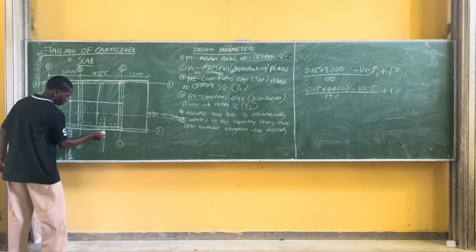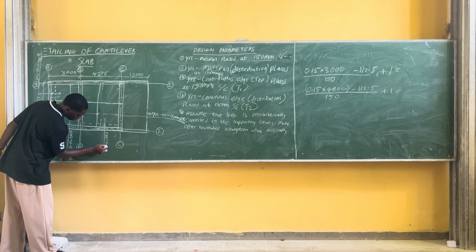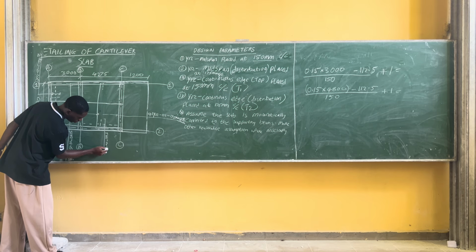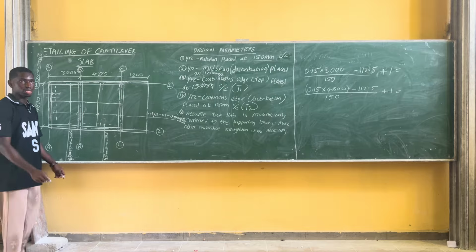So I'll put here 5Y12 bar mark 04 at 150 millimeter center to center T1, which is giving us this.